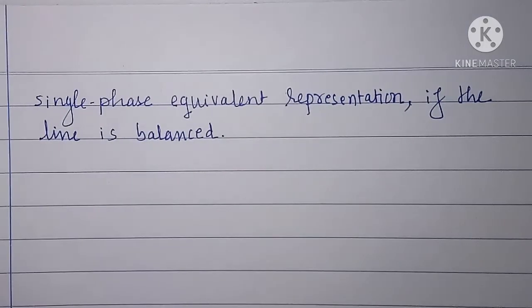the transmission capacity, that is how much power at the given voltage, mainly depends on the inductance and capacitance, because the resistance and the conductance are very small. The resistance used for the analysis of transmission line performance is the effective, that is AC resistance.